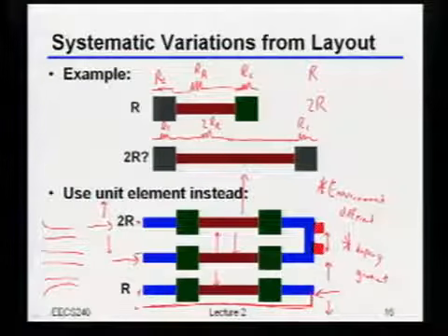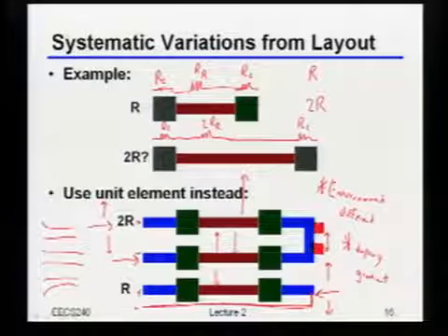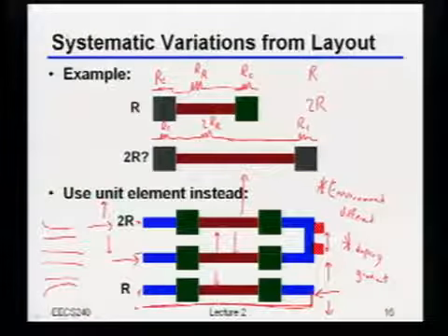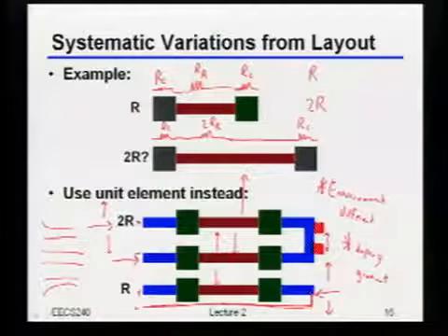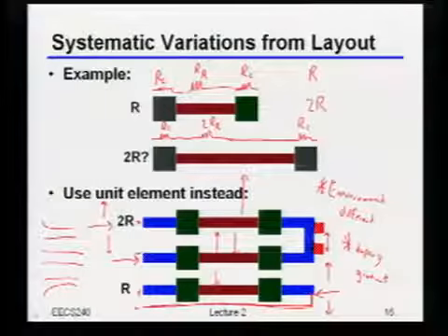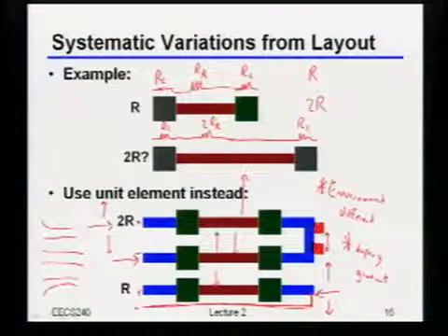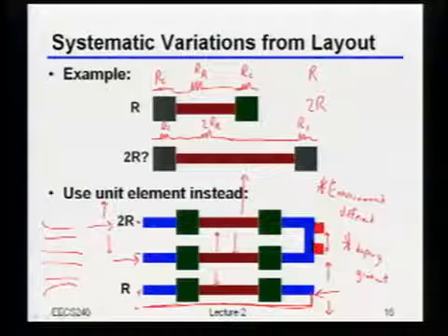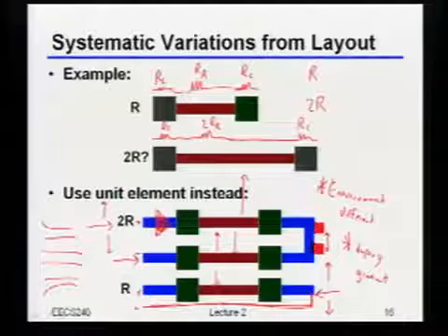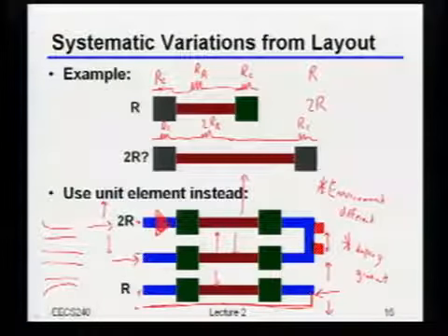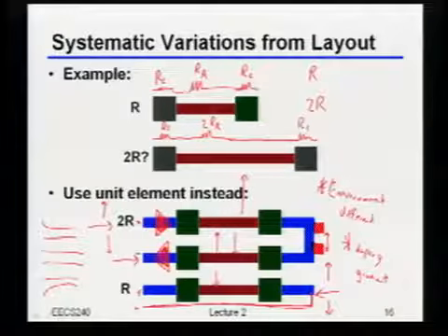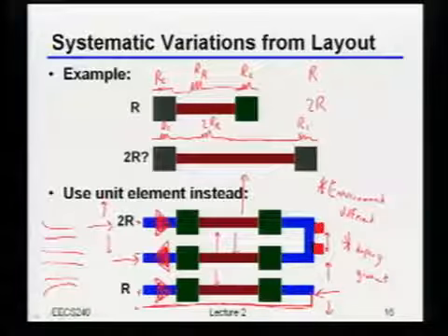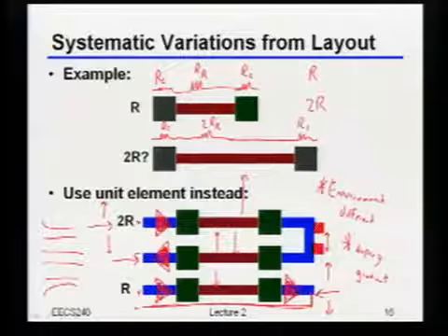Now, if you stare more closely at this, you might actually see what the problem is. So even ignore those wires around it, but keep track of one more thing. Let's draw the loop of current that flows through here. Let's look at the 2R as an example. Direction of current flow. There we go. You got it. If I look at the 2R, current flows in on that side and out on the bottom, whereas in this bottom thing, current flows in over there, and of course, out over here.